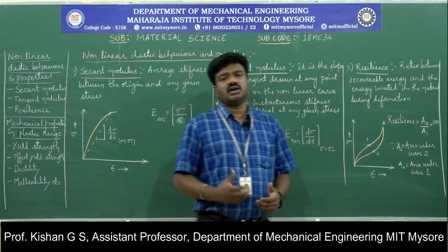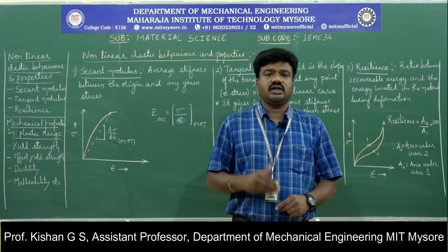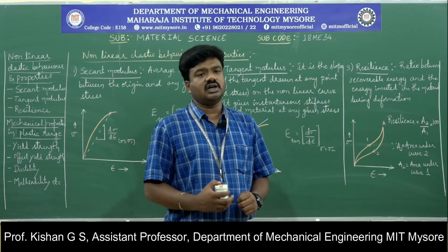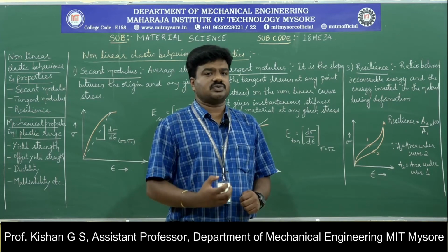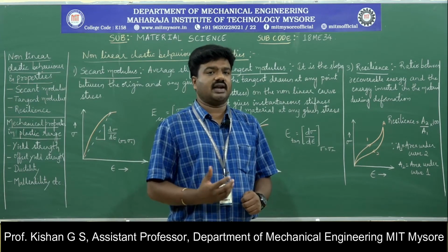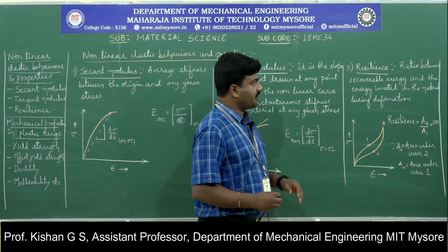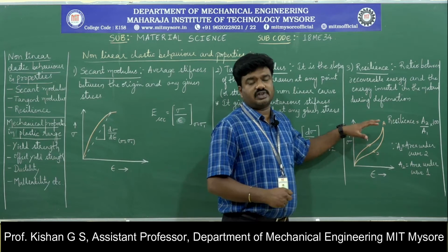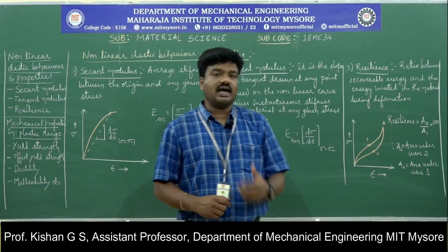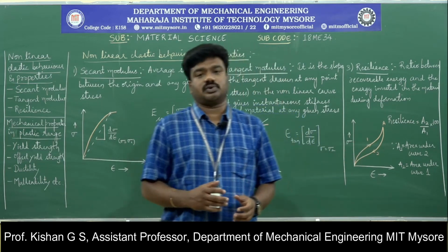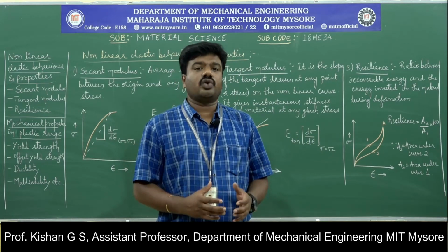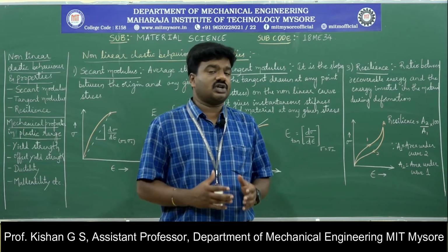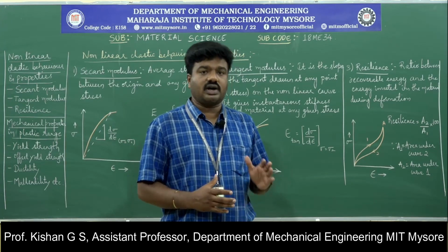We have defined the term resilience even in the linear properties in the elastic region itself. That is the capacity of a material to release the energy which is absorbed once it is being loaded in the elastic region. So here also, the resilience will be taken into account even in case of the nonlinear behavior. Though we cannot come across the proportionality limit here, we are going to observe the area under the curve which represents the condition of a material once it is being loaded and once it is